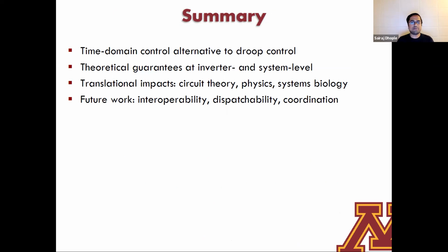But in addition to performance benefits, I'm also able to get several theoretical guarantees on performance, right? I'm able to get theoretical guarantees on dynamic performance, both at the inverter level, as well as at a very broad system level. Okay, and that's something that you may not be able to get very easily with Droop.